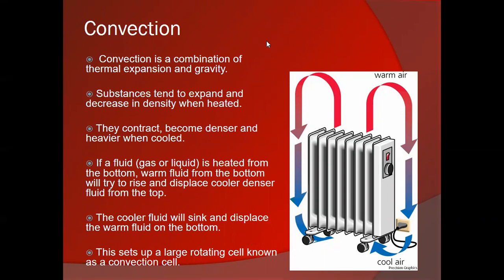Pulls the air into it, the cold air, okay? And then as the cold air comes into these fins, it will heat up and leave the structure as it goes up here. It's getting warmer and warmer and warmer. It'll leave the structure as warm air, okay? Because it's buoyant, it weighs less, and that'll pull even more air into it. So you don't even need a fan to transfer the energy from this hot structure.